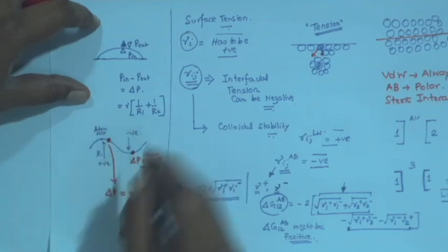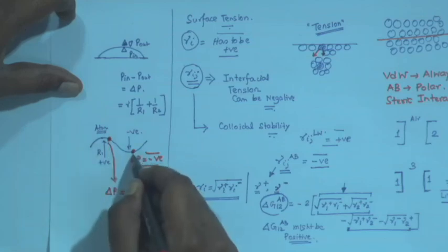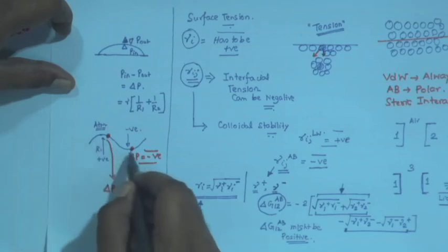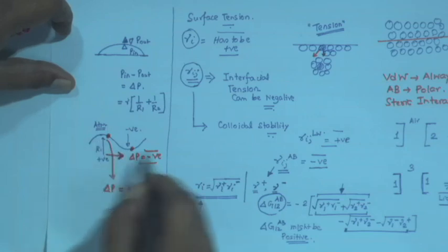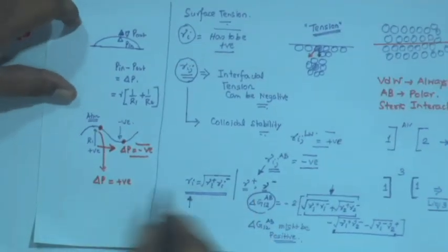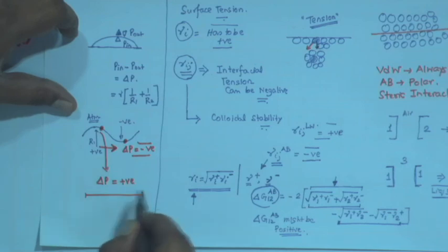What it means is that, outside pressure remaining constant in both the cases, the pressure inside at this point is going to be higher than the inside pressure here. We always know that if there is a pressure difference, it triggers flow. So, you can expect an undulating surface like this to have some stabilizing flow from this point to this point, and the level should flatten down, which is of course valid because a flat level for a film or a liquid represents a lower surface area configuration.